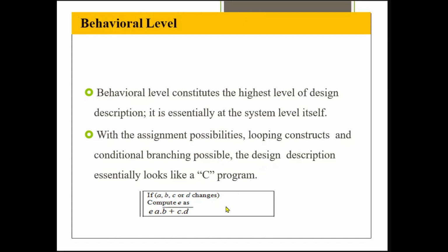If you look at an example here, E is the output, where you have AOI logic. An AND operation is performed between inputs A and B, and C and D, and then they are ORed together, and a complement is applied to this logic. So first the AND operation, then the OR operation, and then an inverter operation. It's nothing but AOI logic. After performing this AOI logic, the output is assigned to E.